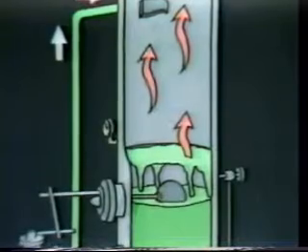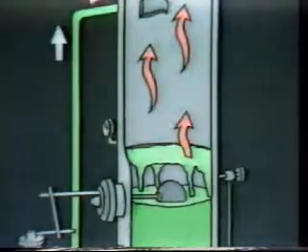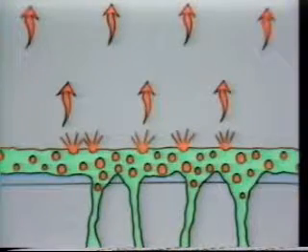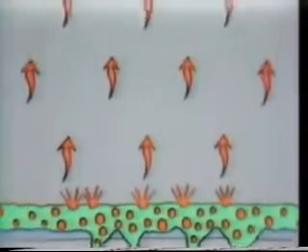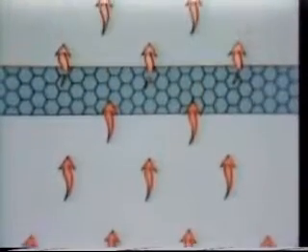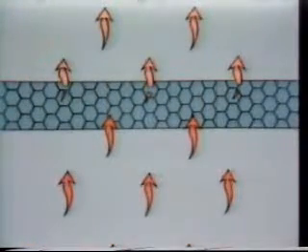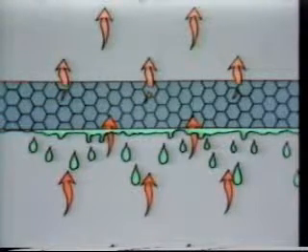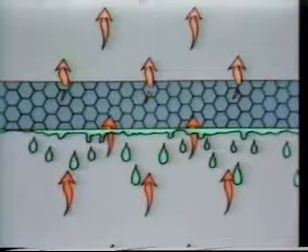Often the separator includes a system of baffles which spread the liquid out as it drops to the bottom of the vessel. This allows any gas bubbles carried in the liquid to easily escape. The gas phase, which is directed to the upper portion of the vessel, is usually passed through a mist extractor to remove minute liquid droplets entrained in the gas. This one, for example, is made of knitted wire mesh. There are other methods used to perform the same operation. We engineers know that a higher volume of ultimate oil recovery can be achieved if gas is removed from contact with the liquid as separation occurs.